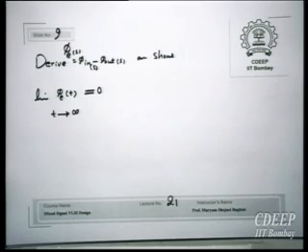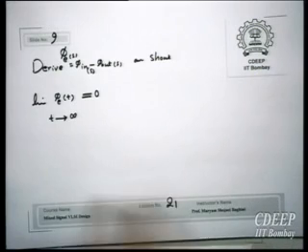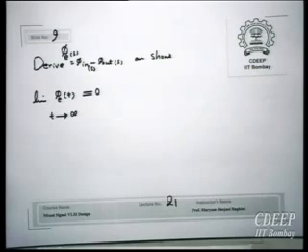You know actually what happens? Type 1 DLL is like type 1 PLL. Type 1 DLL for phase is like type 1 PLL for frequency. That's why these two give the same results. If you have type 1 DLL with phase as the output and type 1 PLL with frequency as output, these two will have similar transfer functions. And frequency error is 0 in type 1 PLL. Therefore, phase error is 0 in type 1 DLL. Interesting.